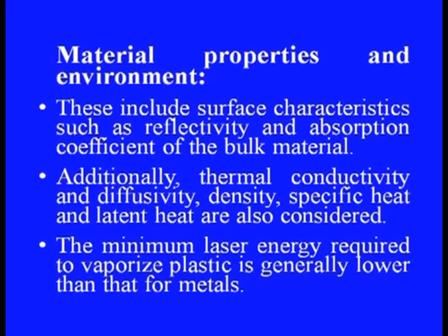Additionally, thermal conductivity and diffusivity, density, specific heat and latent heat are also to be considered. The minimum laser energy required to vaporize plastic is generally lower than that of metals. Therefore, accordingly the laser power is to be selected as per the material requirement. Now, let us move on to the applications of laser beam machining.